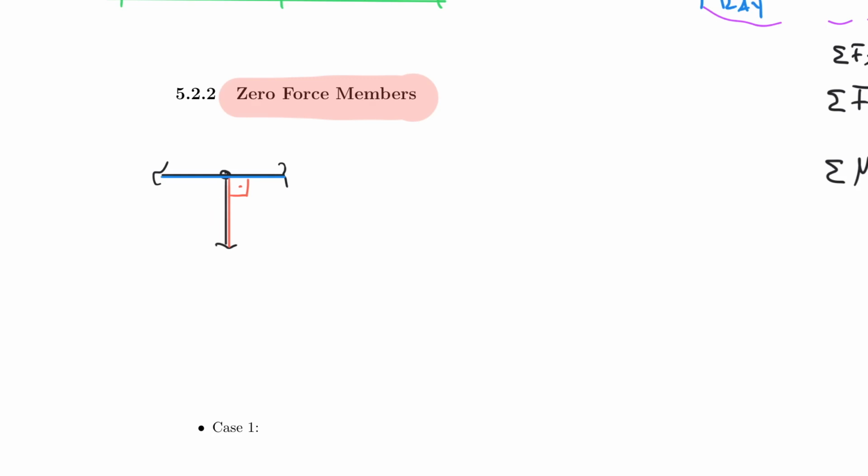And therefore, this actually works for any scenario, not just for the perpendicular case. I can have the very same scenario, so let me redraw the system here. And let me join a third one, which now is actually under an angle. And often students think, now that it's under an angle, it cannot be a zero force member anymore. But remember, we cut through the system here and here and here. And the red component here, the one that is not parallel with the other two, has a vertical component and has a horizontal component, something we dealt with very early in this class.